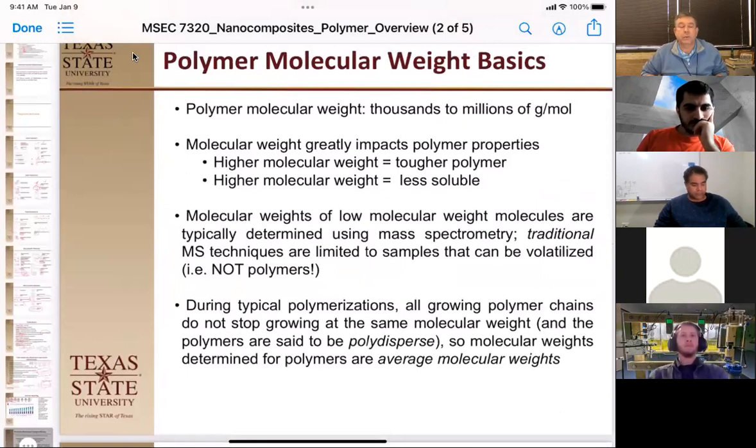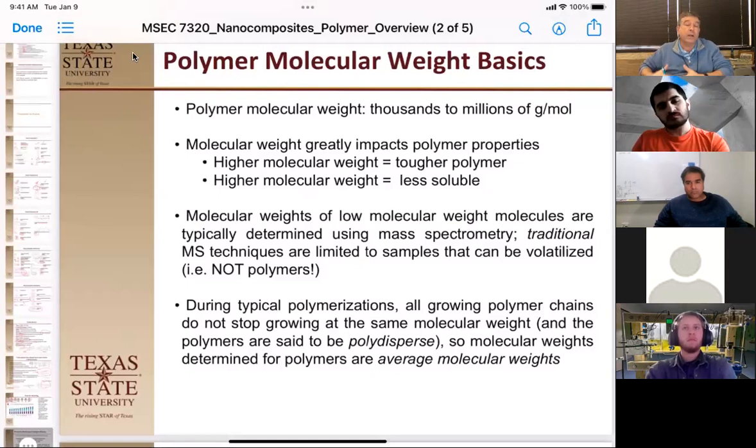Okay, so for example, I have a polymer I'm making in the lab right now. It's about 32,000 molecular weight. If I go above that, it gels out and never redissolves. If I go below that, it kind of powders out. So I have to be very precise about trying to get it exactly at the right place. But things like polyethylene, you want it in the millions. It's tougher, it's easier to deal with.